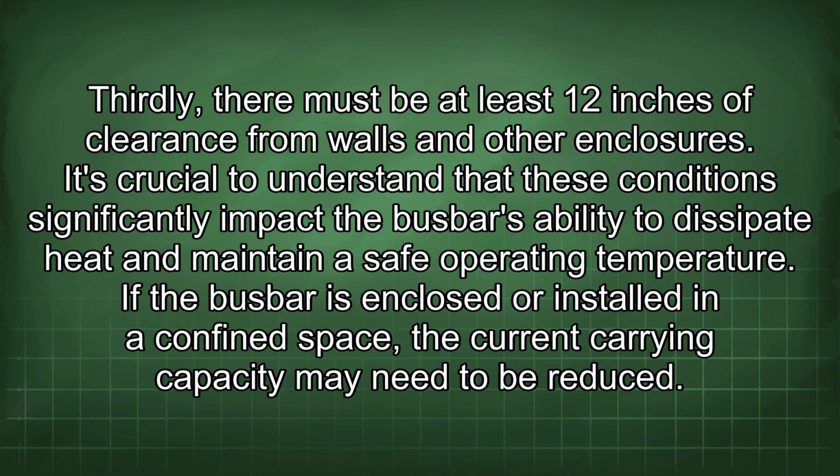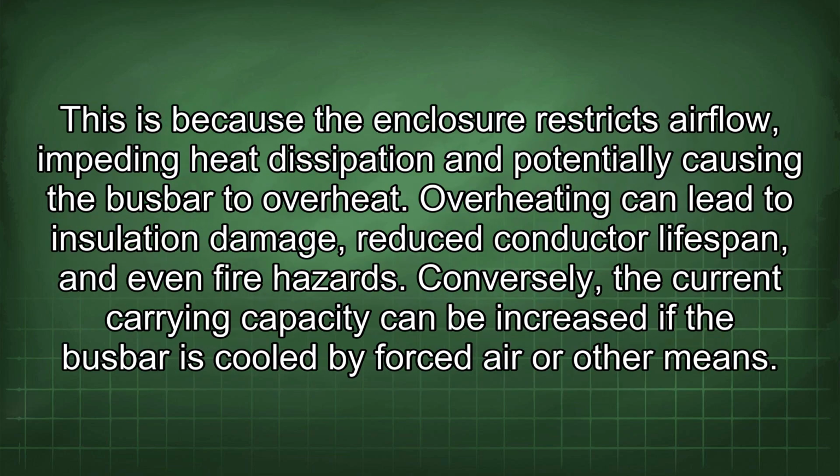It is crucial to understand that these conditions significantly impact the busbar's ability to dissipate heat and maintain a safe operating temperature. If the busbar is enclosed or installed in a confined space, the current carrying capacity may need to be reduced. This is because the enclosure restricts airflow, impeding heat dissipation and potentially causing the busbar to overheat. Overheating can lead to insulation damage, reduced conductor lifespan, and even fire hazards.